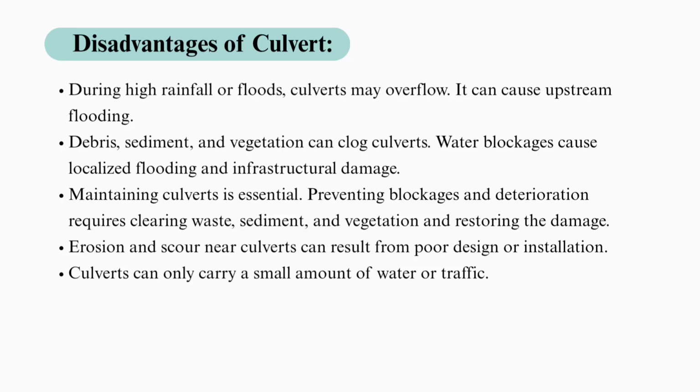Then the next point is that maintaining culverts is essential. Preventing blockages and deterioration requires clearing waste, sediment and vegetation and restoring damages. Erosion of the soil near the culverts can result from poor design and installation. Culverts can only carry a small amount of water or traffic. So these are the different disadvantages of culverts.